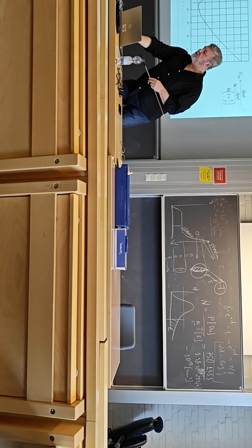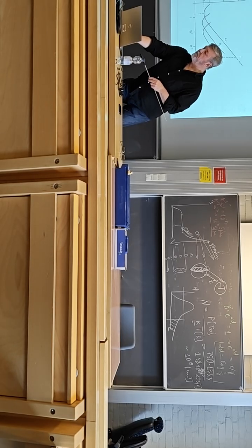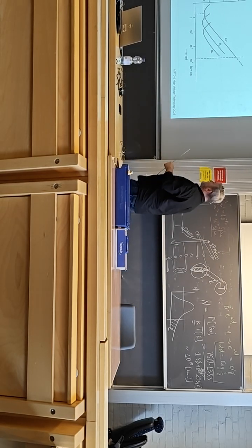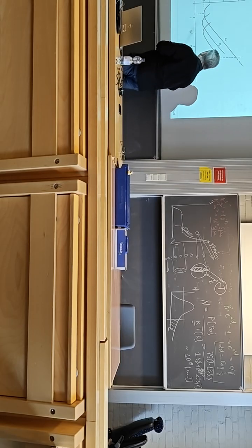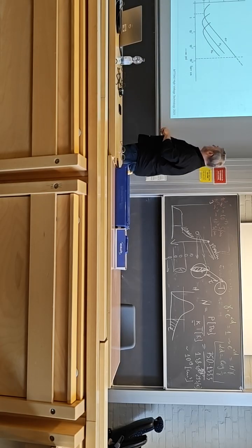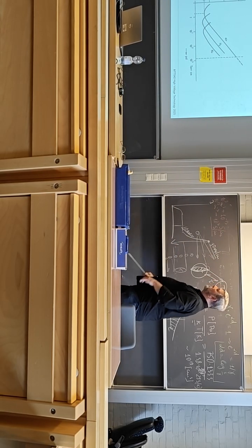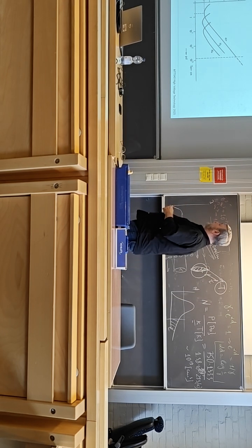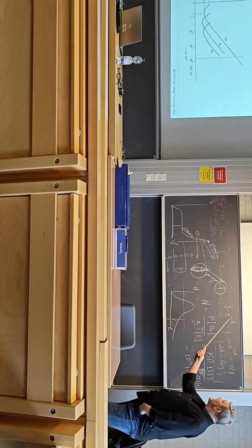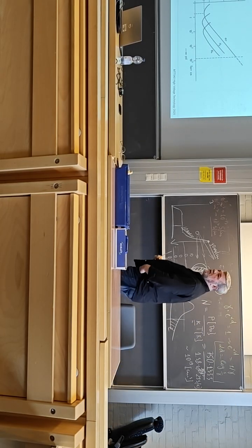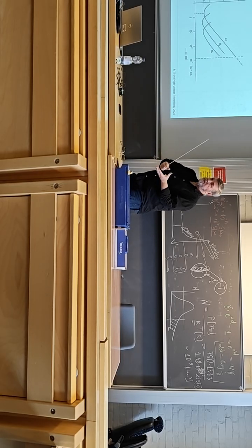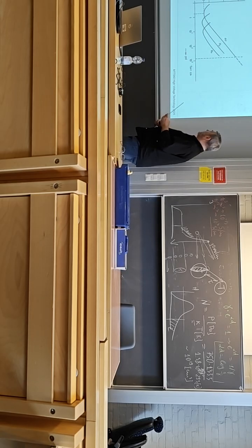Let's look now here, and then we will discuss why we have a minimum. As I said, this is unique for each gas or composition of gases. This is for air, this is for hydrogen, this is for neon. So if you have a mixture of gases, you can actually tailor the breakdown voltage. The uniqueness of this comes from the fact that alpha is unique for each gas. Conditions for ionization are unique because they are defined by the cross-section, distribution of energy of electrons, and so on.